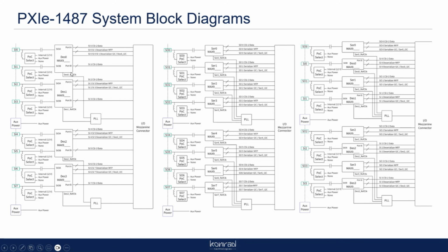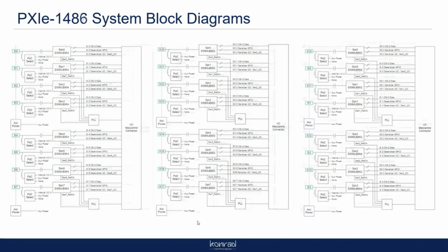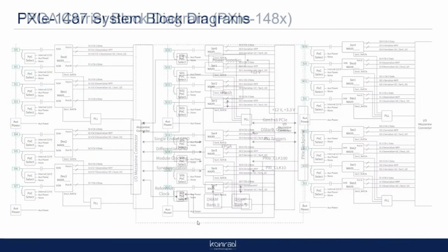So this is a little bit of a gotcha on the GMSL one, is that if you want four completely different data rates, four completely different cameras, that's fine. You just have to spread them out, or you might need a second card depending on that, right? So that's a little bit of an interesting thing we ran into. It's in the documentation, it's just not very clear to the users in my mind. And then 14, the other one.